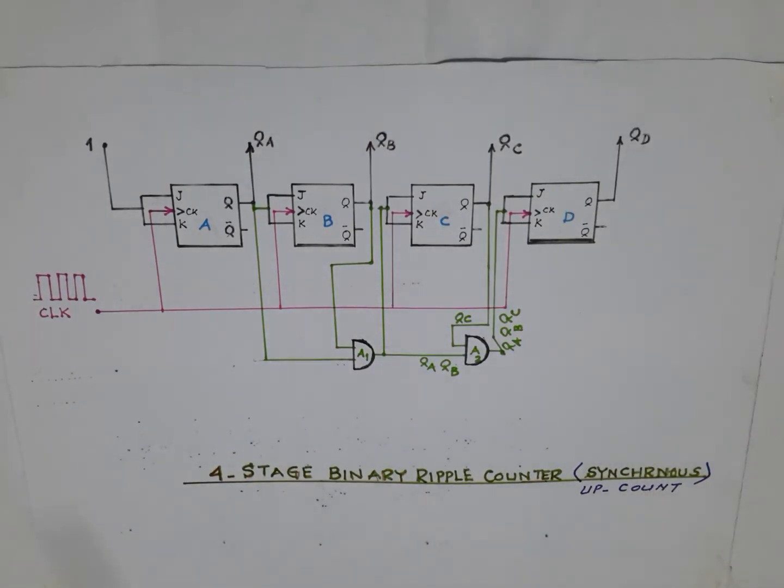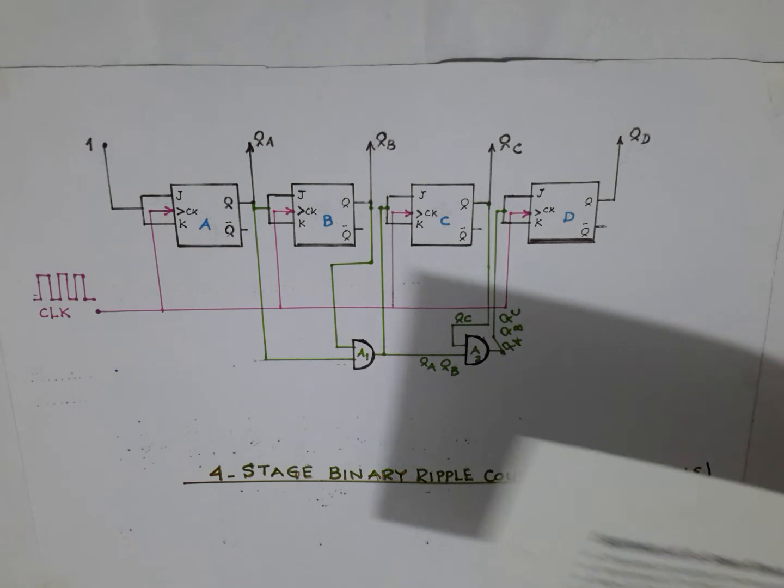Now since all the flip-flops toggle simultaneously, this problem which we were facing of propagation delay has been overcome, and there is no question of B waiting for A to change the state, C waiting for B to change the state.